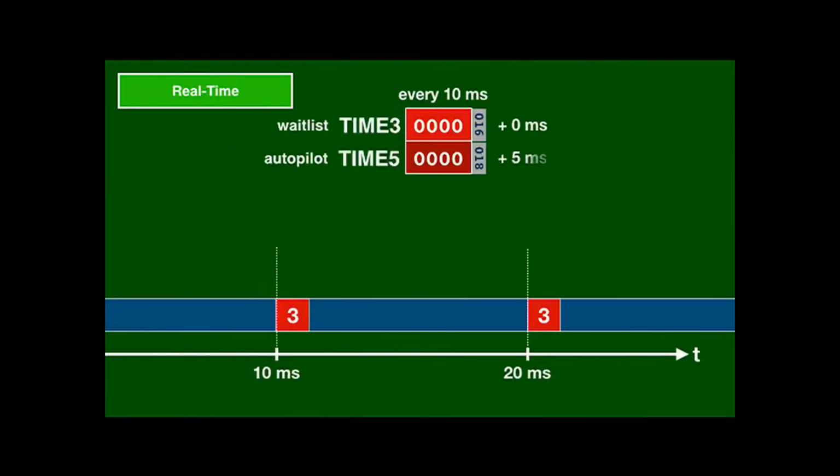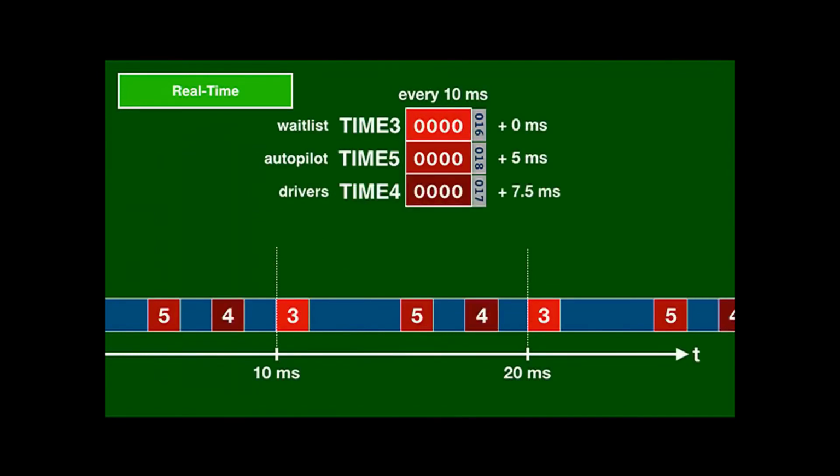Other timers can fire at the same rate, but are offset, and the work triggered by them is designed to be short enough to never overlap with the next potential timer-triggered work. This is complicated by device interrupts, which can come in at any time. The duration of an interrupt handler causes latency, and the maximum duration will reduce the allowed time for the timer handlers. The core system software makes no guarantees about the timing. It's up to all the components to cooperate so the real-time goal can be met.